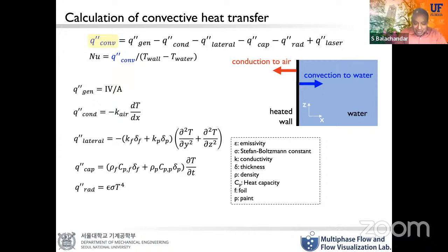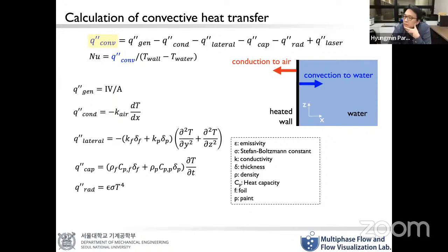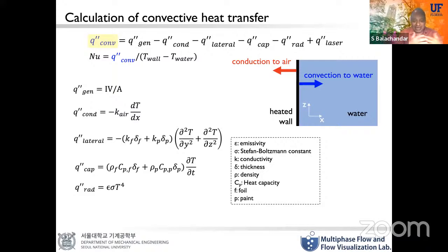You talk about mixing, but to me, for a bubble plume this is probably natural. In a general context of mixing, this is very special, that you have a lower layer of fluid mixing with the upper layer of fluid. Sometimes we might want to mix a homogeneous fluid as a whole.